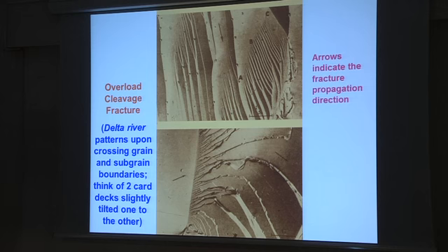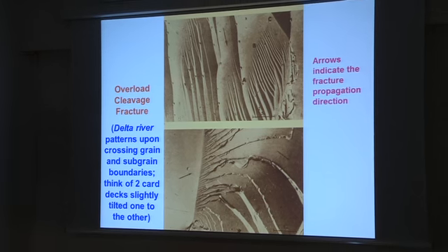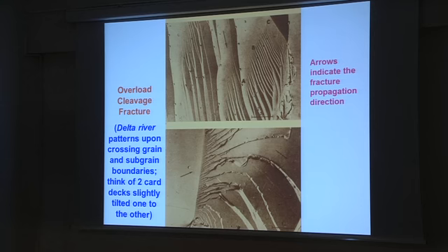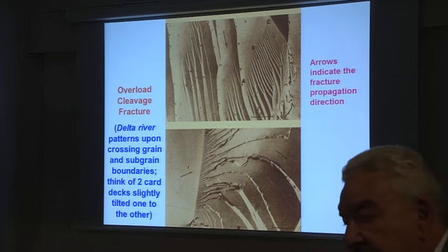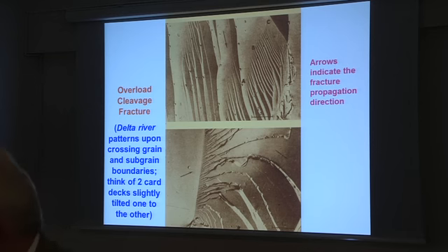You are more familiar, when we speak of cleavage, with what is termed the delta river pattern. You know, a river can go into the sea with a delta. And this is an inverted delta, because let us consider this case in which we have a boundary. And this is the cleavage plane in the previous crystal.